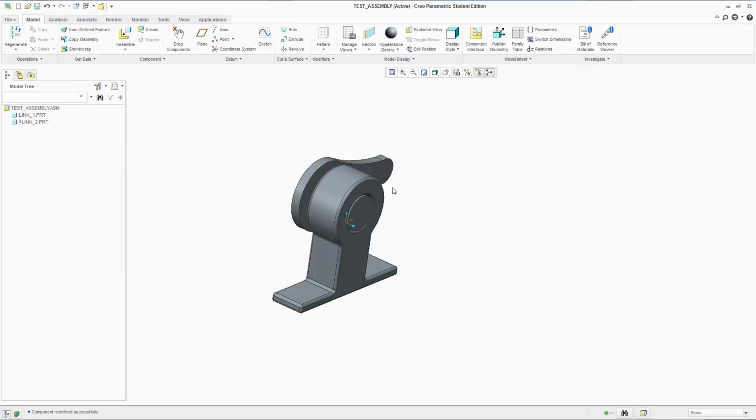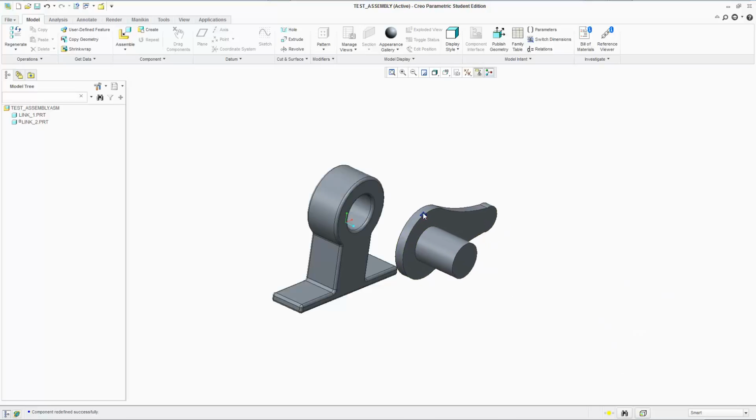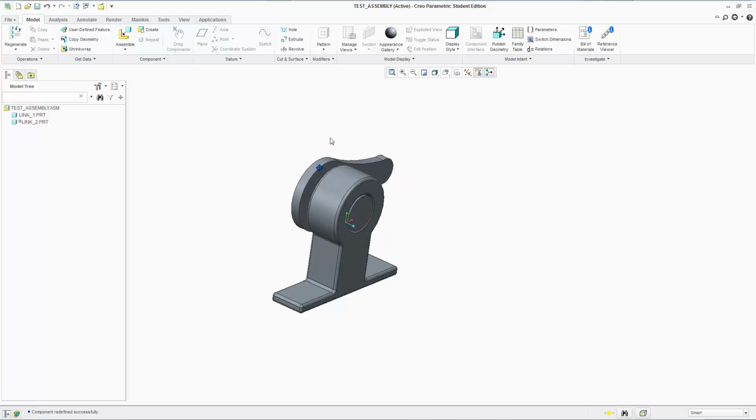So I'm going to hit OK, and press Control Alt, and then click and drag. I'm only allowed to go in the forward direction. When I click and drag and try to go backwards like this, at the point where we set 0, it's not allowing me to go back from that. It's only allowing me to go forward. So we know our minimum is right here.